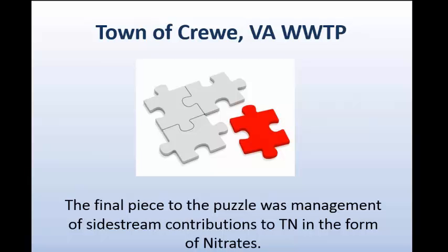We also saw them when we were going through the dewatering process. Dewatering is when we take sludge from those aerobic digesters and run it through what's called a belt filter press, which basically squeezes the water from the sludge, giving you a dry cake, which you can ultimately dispose of. Whenever we were doing our dewatering or decanting, we were seeing these spikes.